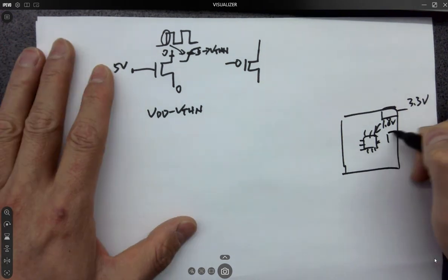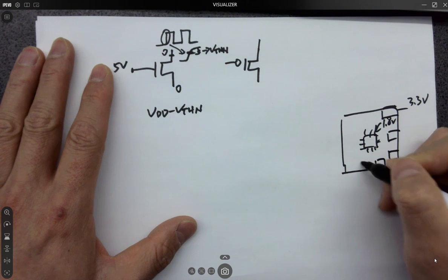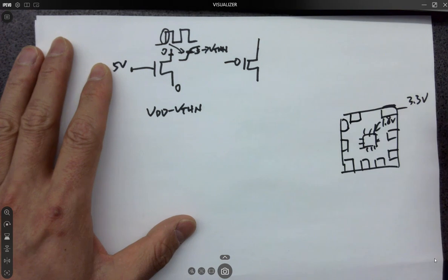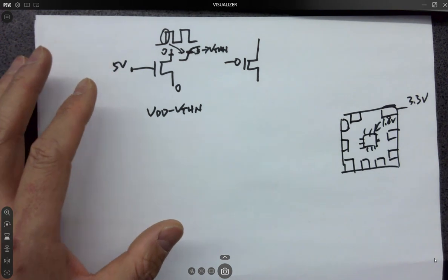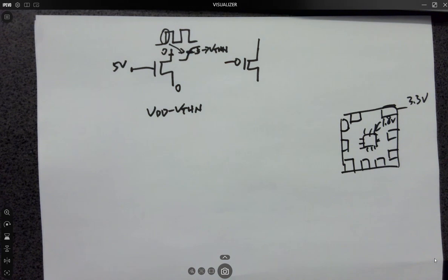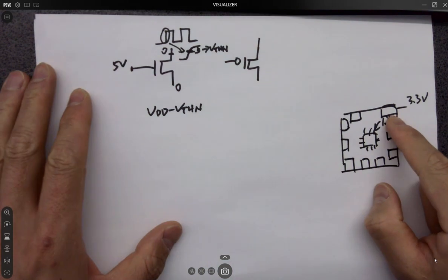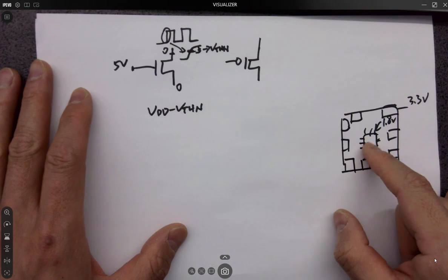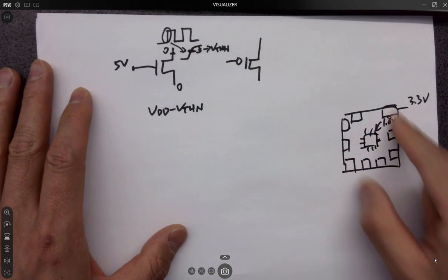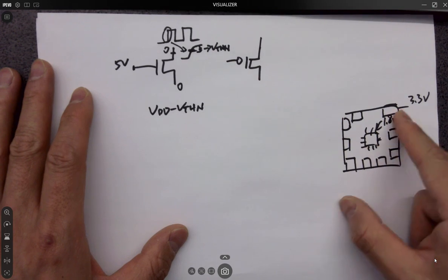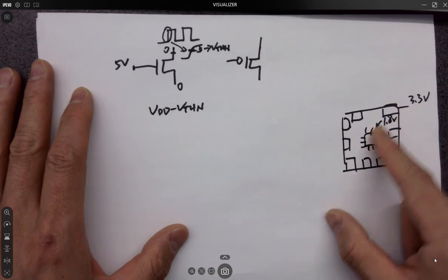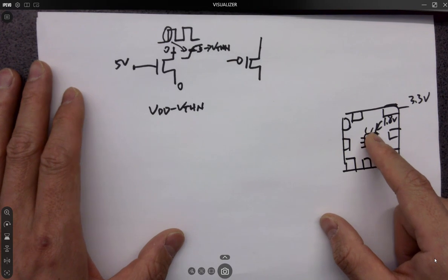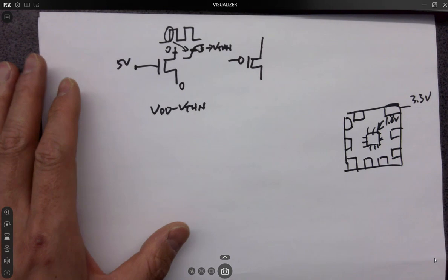But for all the rest, sometimes the pads have buffer circuits. Remember all these pads? These pads are the metal 3 openings on top of the chip. All these pads have some buffering circuit in them, and these buffering circuits are getting 3.3 volts. But in order to save the overall power consumption, we step the 3.3 volts down to 1.8 to supply power to the core. So the core is taking only 1.8 volts VDD.